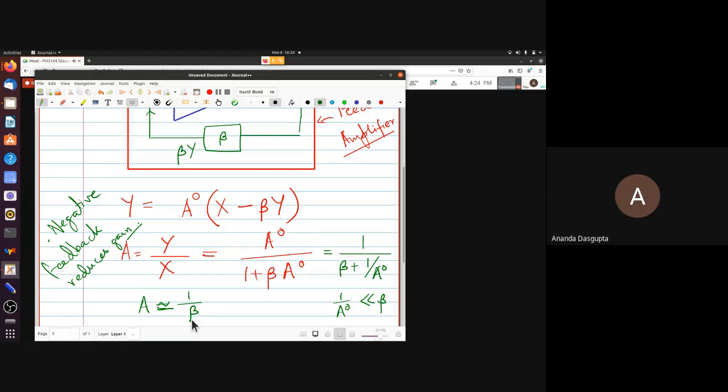In fact, even if you were worried about temperature varying a lot, first of all, you may be able to put your negative feedback part of the circuit far away from transistors and other things which tend to heat up a lot during the operation. So the temperature of your negative feedback network may not change very much. But even more importantly, if you are using two resistors out of the same material to have a potential division, the resistances are going to change with temperature in the same manner. So the ratio, which is what decides what fraction will go out, will be temperature independent.